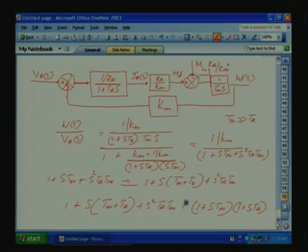So, we got the thing in time constant form, 1 plus Stm, the standard form, the pole-zero form. So, if you do this way, the final motor transfer function, input output, that means we are giving Va, see all these blocks we do not require now, we are only looking at the output omega s with respect to Vs.